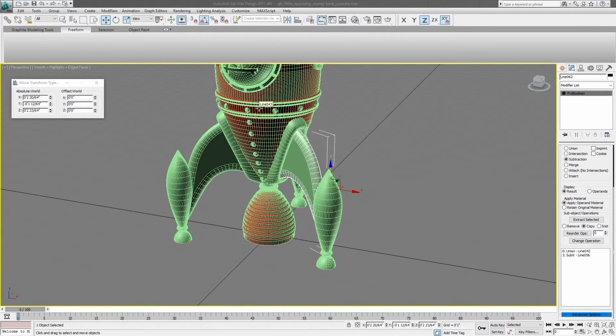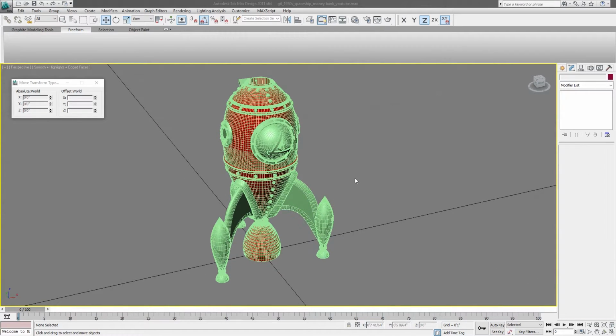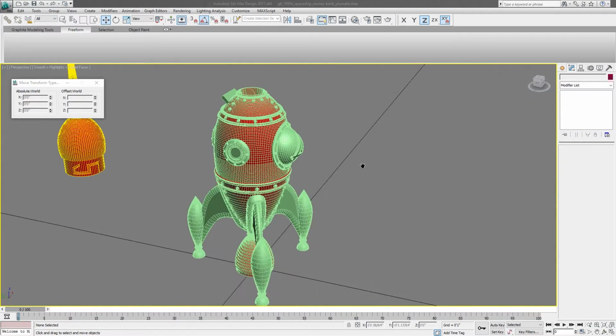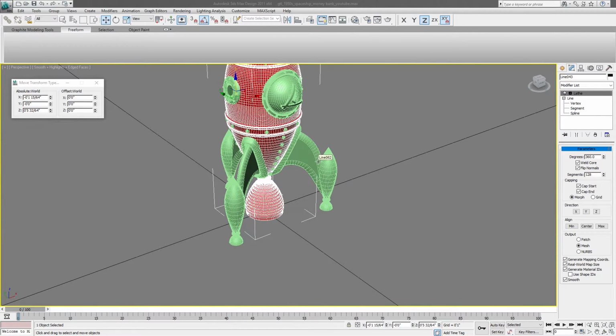And you'll find with the next steps, as we start using the Boolean operations, you're going to spend a lot of time cutting things out and trying it. It's not going to work right. You're going to have to come back again, tweak the original geometry, cut it out again. It's a bit of a process, but once you're done, you should have a very clean, simple model that you can go ahead and export as a solid manifold model.